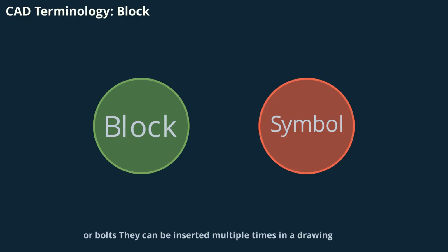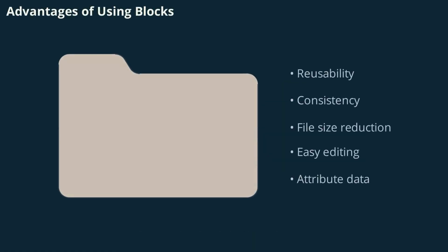They can be inserted multiple times in a drawing, reducing repetition and file size. Blocks streamline design workflows, ensure consistency, and make editing easier. Modifying a block definition updates all instances, and blocks can contain attribute data for bills of materials, making them invaluable in CAD projects.